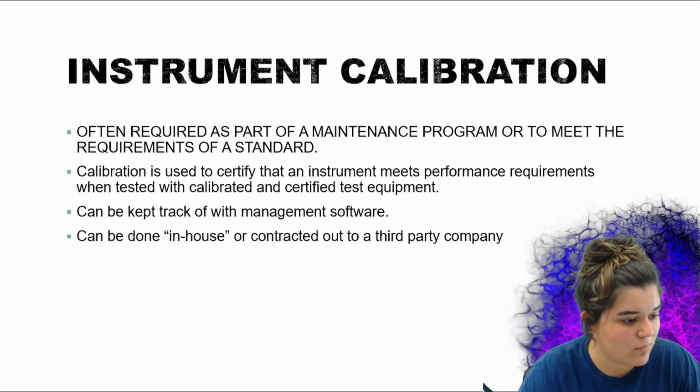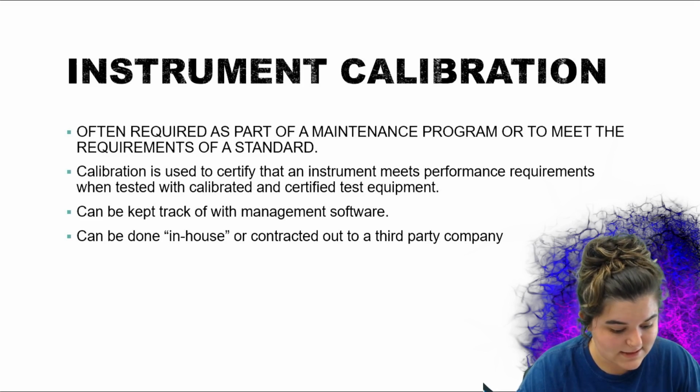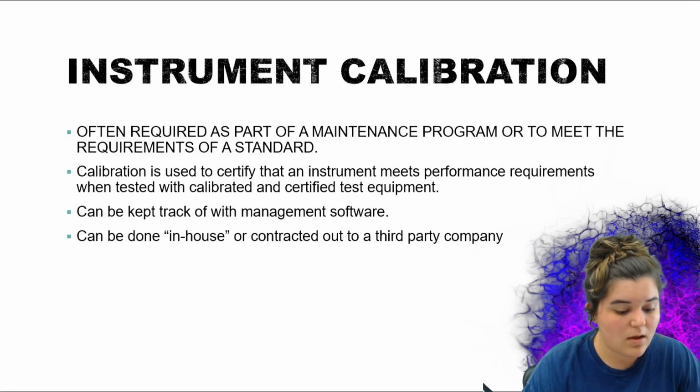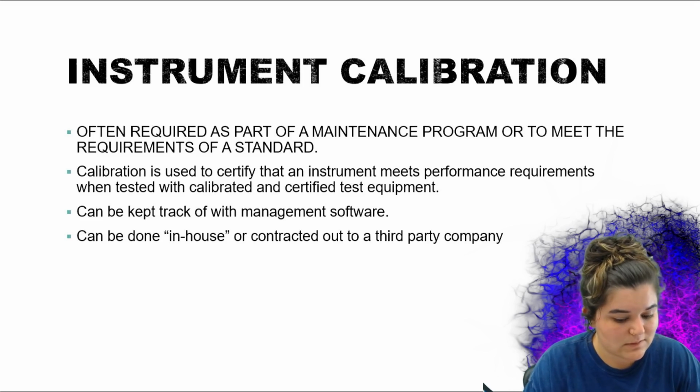So, for example, when I worked for Southern and they would go around and do testing on turbines and boilers and stuff of that nature, before that equipment got sent out to the plant to be set up to where they could conduct testing, everything had to be calibrated. So all the way down to the thermocouples, they would have to calibrate them, run the software, and prove that they were calibrated to a certain extent before they could be used. So you had to prove that everything was in tip-top shape before you could test something.